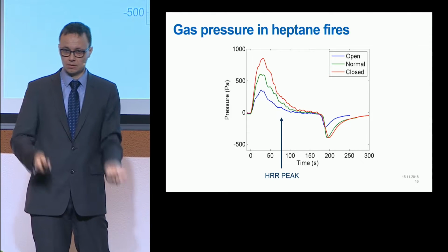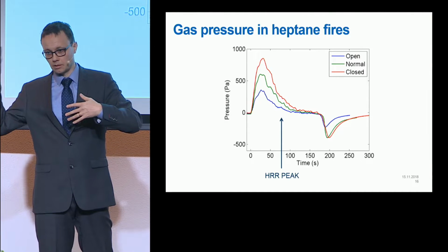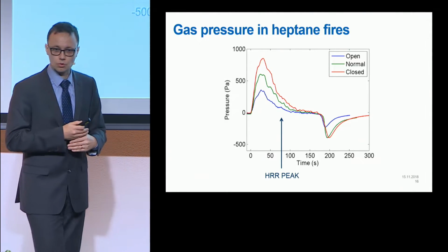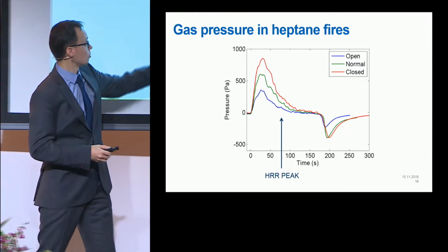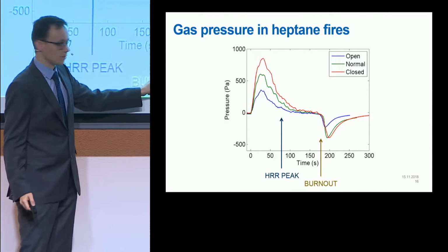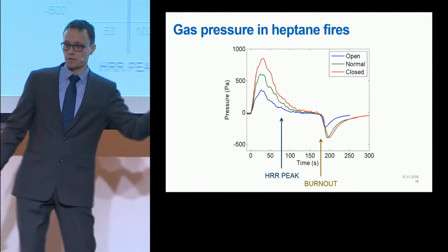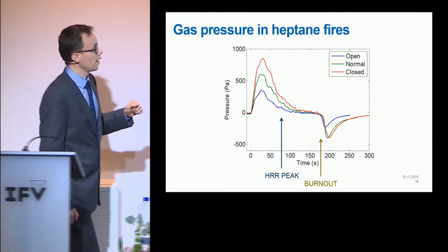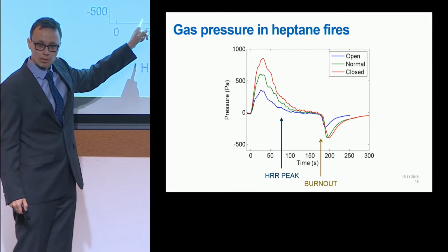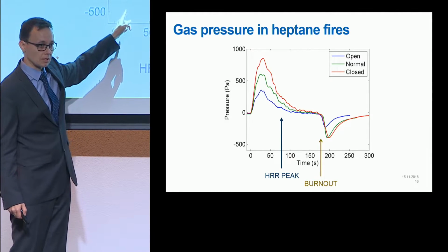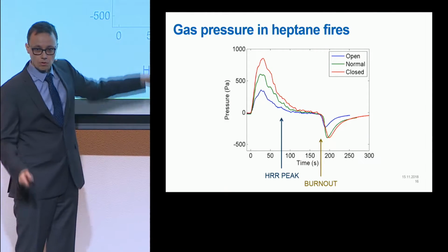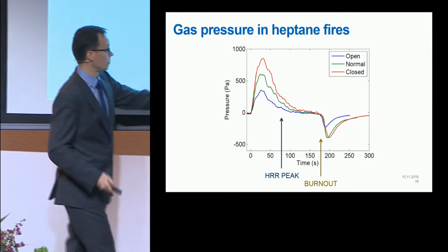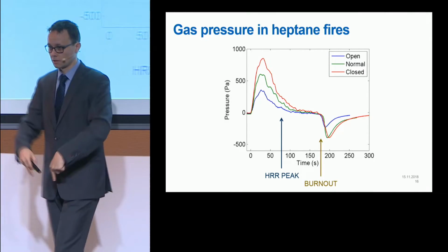These two things balance, source and the drain. Source is going to decrease and the flow through the envelope is going to increase, and therefore we have the peak there. Then over here we have the burnout of fuel after that sudden negative peak of pressure. And we can see in the measurements of ventilation duct flows how here all the ducting is going to flow out from the apartment, and over here all the flows are going to be inwards.